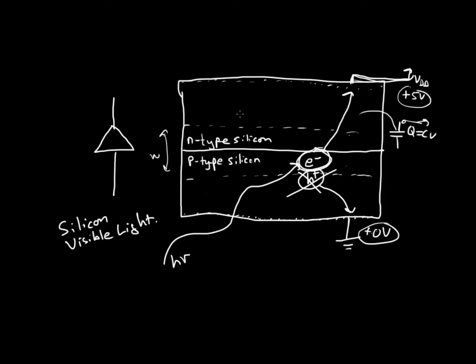Okay, now as I mentioned, this is silicon, and we're talking about the energy of visible light, h nu, where the speed of light equals the wavelength times the frequency, and you use this term to calculate the energy. What kinds of photons, what kind of electromagnetic radiation is silicon going to be sensitive to? Well, I scroll down. This is a PIN diode.